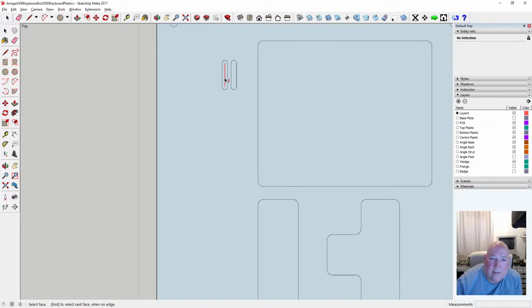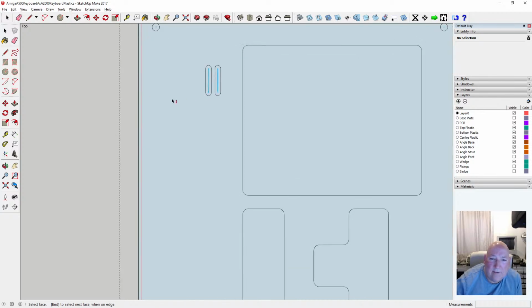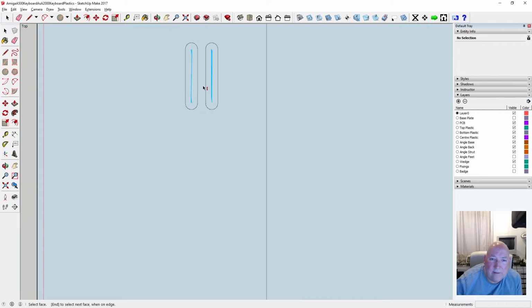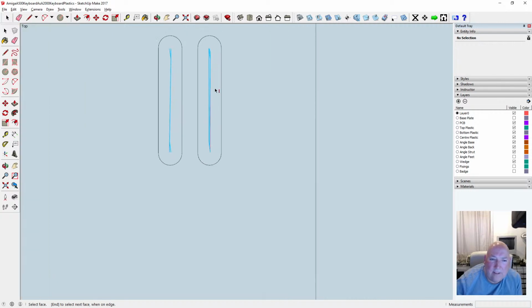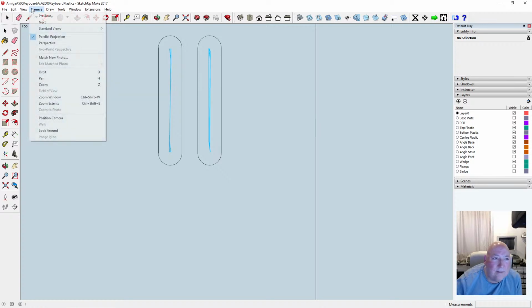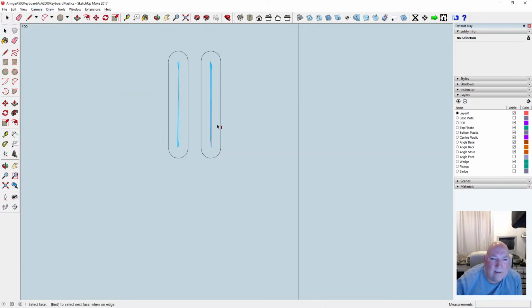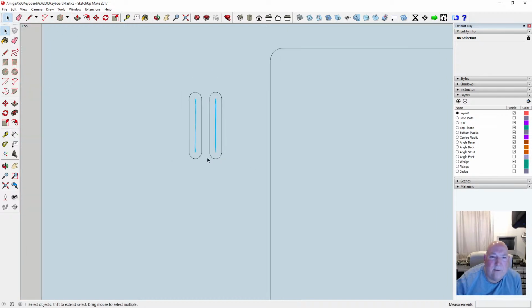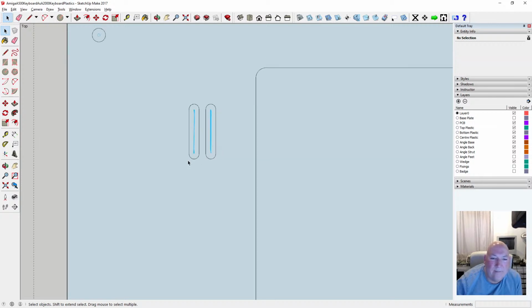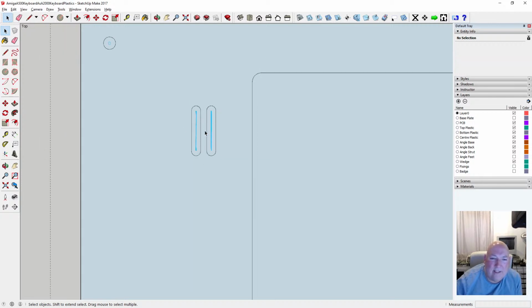That's actually better, isn't it? That is. I'll tell you what, we'll do them as well. That's better than the one I did up there. It is weird though why it's going like that. Strange. Oh, maybe it's going round because it's... Oh yeah, it's 3.17. What size is this? 3mm. Right, how can it cut a 3mm with a 3.17? Can't, can it really? That's indicating there's an error there.